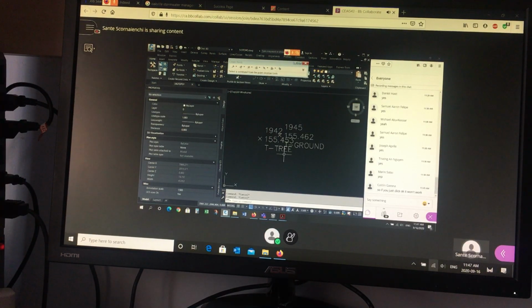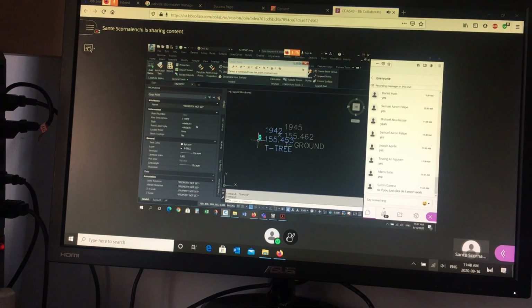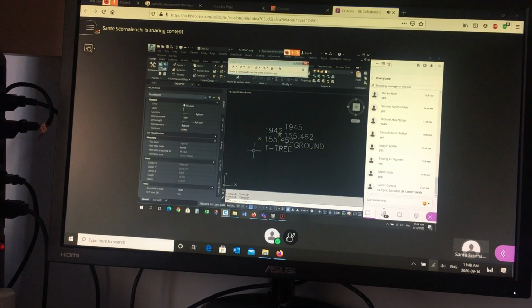So don't hard code like you do with line. Don't make a line red. Make sure the color is by layer. Don't make a line type dashed. Make sure it's by layer. And then you can change the by layer setting. You can change the layer setting so that all the items on that one layer all look the same. So you can globally change the look of everything. Not one at a time, but the whole layer. Okay? So that's why you want these to be set to default. Okay? More about that when we create the next thing called groups. Okay, I'm getting ahead of myself. So does everybody understand styles?